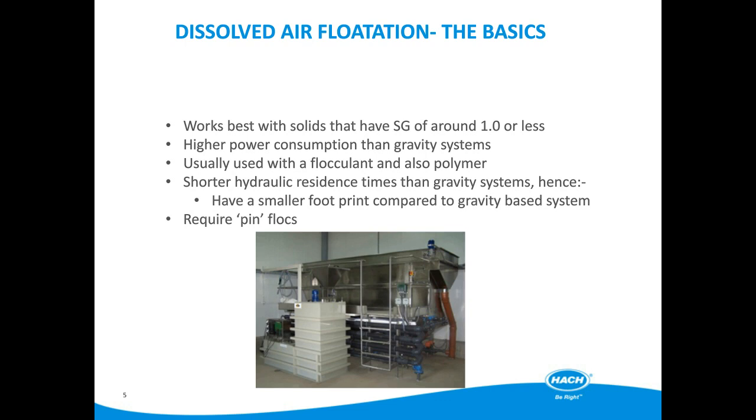Another similar sounding process is SAF, and that stands for Submerged Aerobic Fixed Film Reactor, sometimes with a single F or sometimes with a double F. The SAF process is similar to that of the BAF, but in this case the media in which the biomass is growing is not mobile and does not need the screen or mesh to retain the media. Having said all that, the process being discussed in this webinar is the DAF, or Dissolved Air Flotation process.